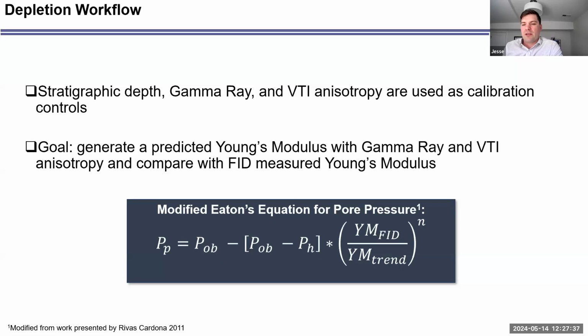So we think many times what we're seeing is we've gone beyond the effective stress the rock is seeing, and you start to see pore collapse or compaction mechanisms start to take hold. So you can see quite a bit of an increase in the Young's modulus when that occurs.